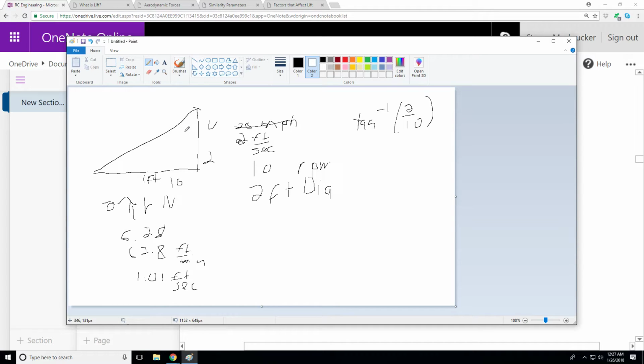And so what this does is, when this pitch is changing, it's helping with the wind. When the wind comes here, the wind is actually grabbing onto the blade and helping you rotate the blade. So it's actually helping you spin the blade around. So in the center of the prop, it's not very useful for thrust, but you'll see on a lot of the faster airplanes, they have a pitch almost parallel to the direction of travel on the blade right there, and that is for the speed. That is for the wind to help rotate the blade, so you could generate even more thrust.